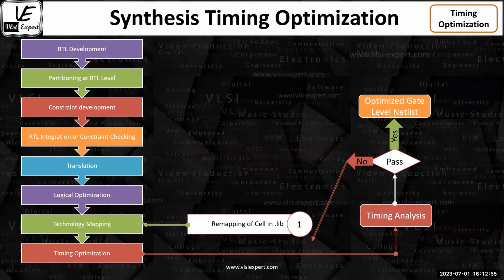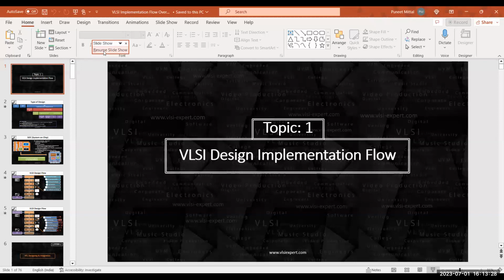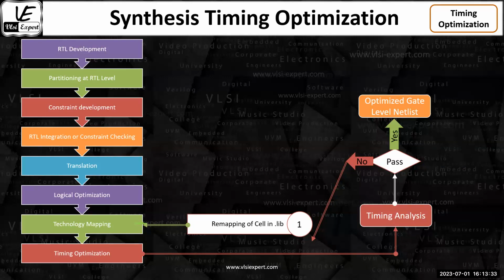Now let us suppose there are 10 NAND gates. You tried everything, and even after that, you are not meeting the 6 nanosecond. Then what is going to happen? This is the portion where the custom and the standard cell based things come into the picture. In a standard cell base, you have a predefined 10 NAND gates, and you cannot make any changes. Even after that, if it is not working, you cannot use the 11th NAND gate.